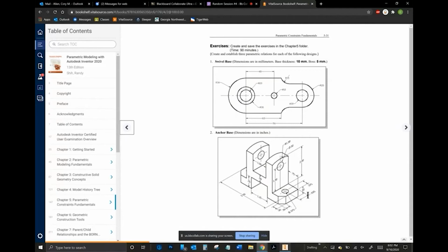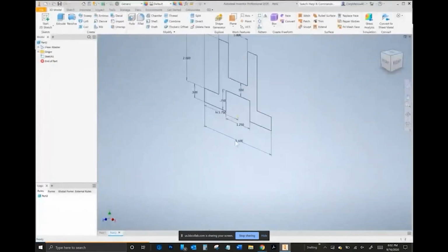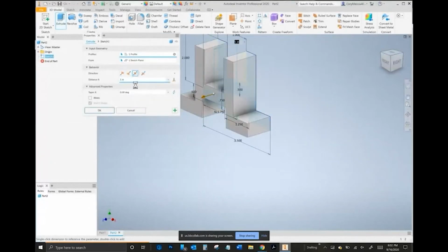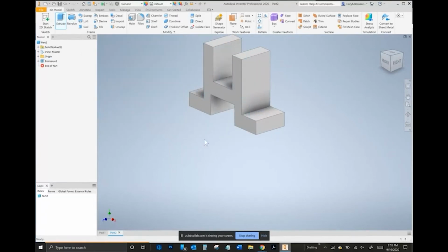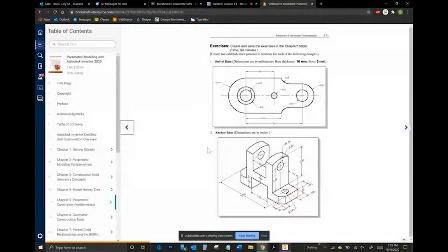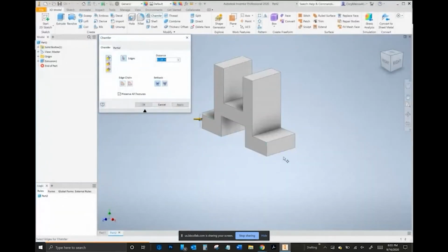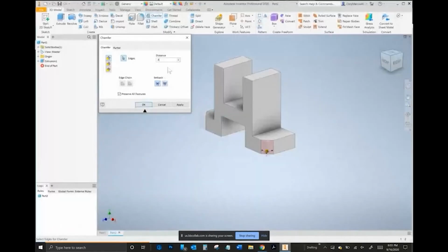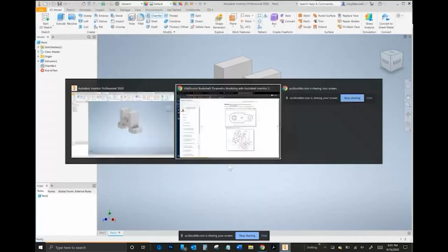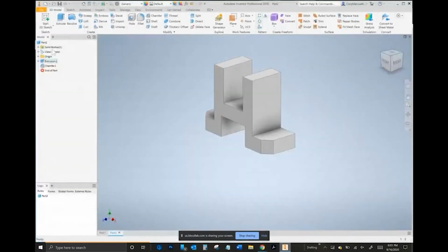Okay, so I'm immediately led to believe that this 0.625 times 2 equals the width, but I'm trying to see if I see an actual width here. And I don't. So let's just see what that would look like if we extruded it. 0.625 times 2. And that's got to be it. Okay, so we'll do chamfers to start since they're pretty low-hanging fruit. And it says 0.3 equals, so we can just do a generic 0.3 chamfer. Okay.